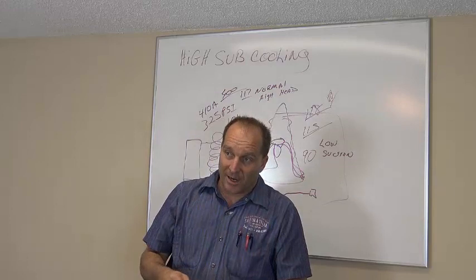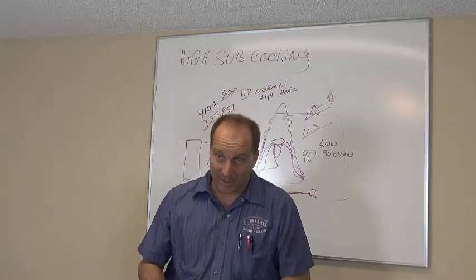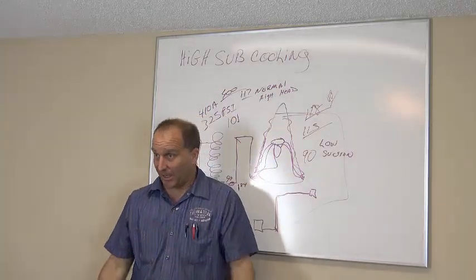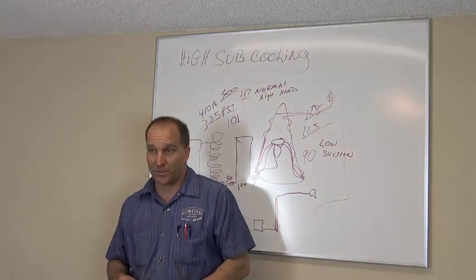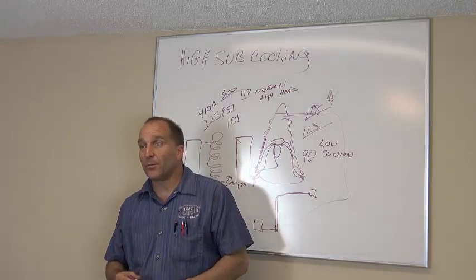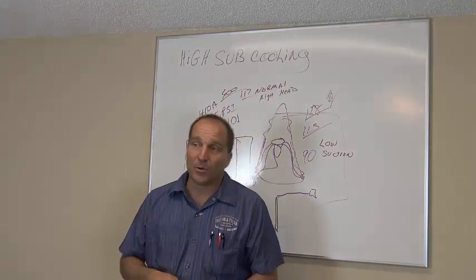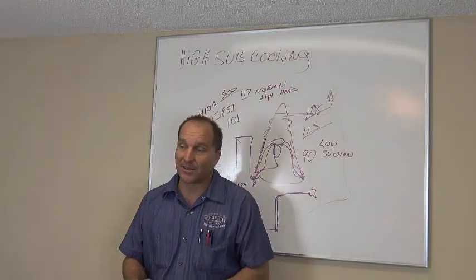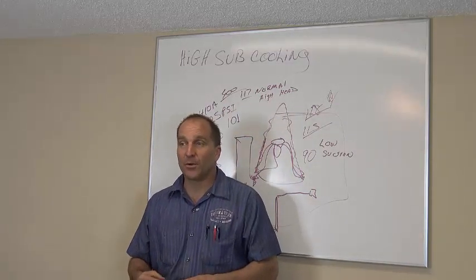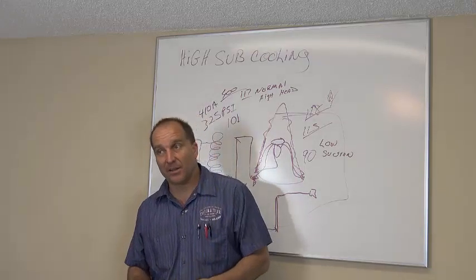You start hosing that condenser coil off and then you spray it with a chemical, it is going to be just black coming out of it every single time because nobody ever cleans both coils. So that's very important when you go to any job. You need to look and know the types of systems that you're going to on a regular basis so that you can determine what kind of system it is. I'm going to give you another example.